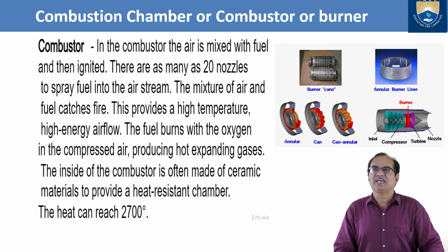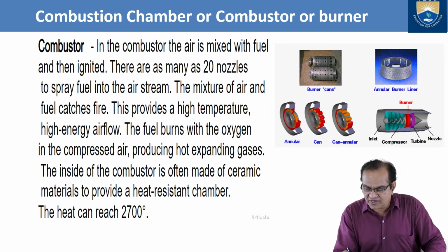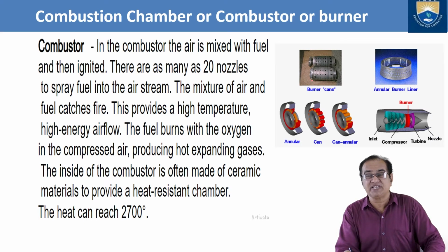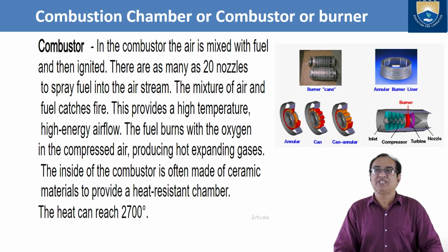In the combustor, the air is mixed with the fuel and then ignited. You see there are different holes, and these holes are properly designed so that the required amount of air and fuel is available for the burning. There can be as many as 20 nozzles to spray fuel into the air stream. The mixture of air and the fuel catches fire.